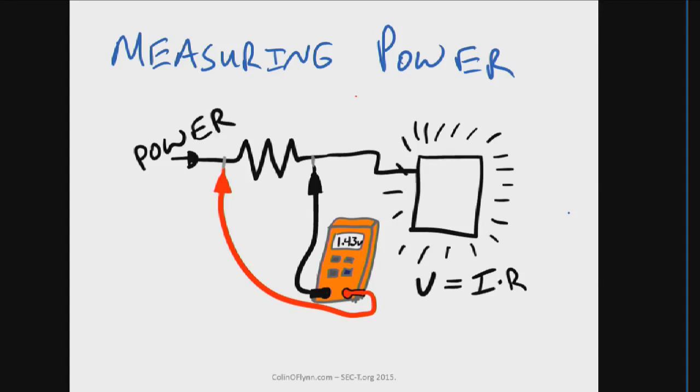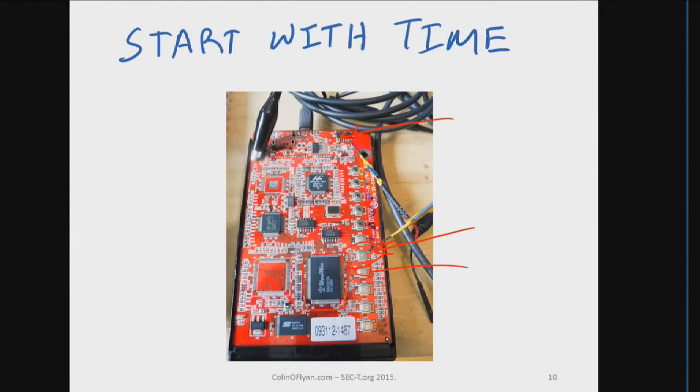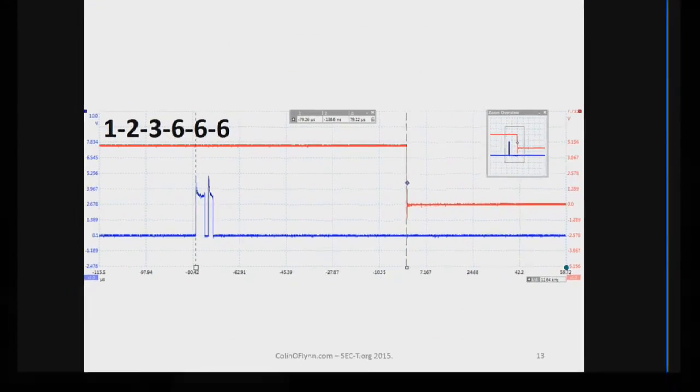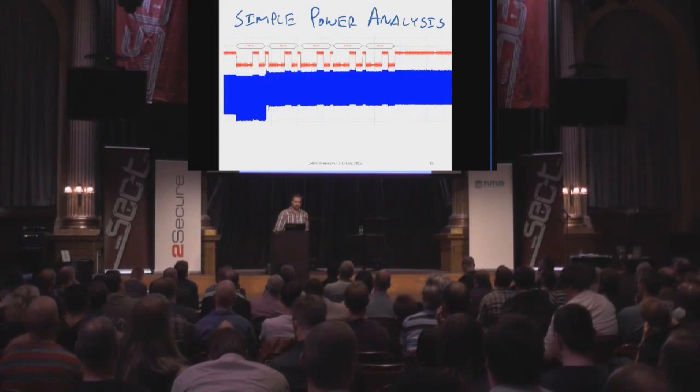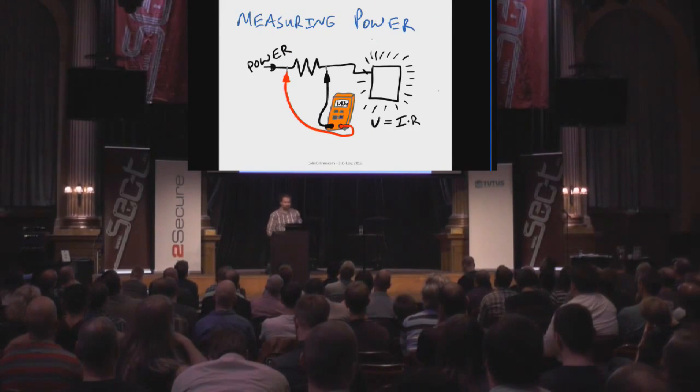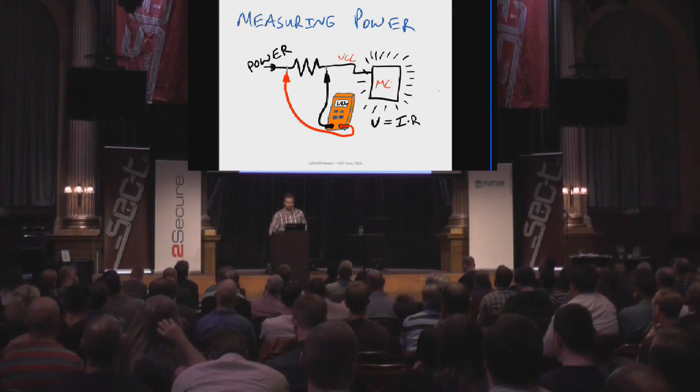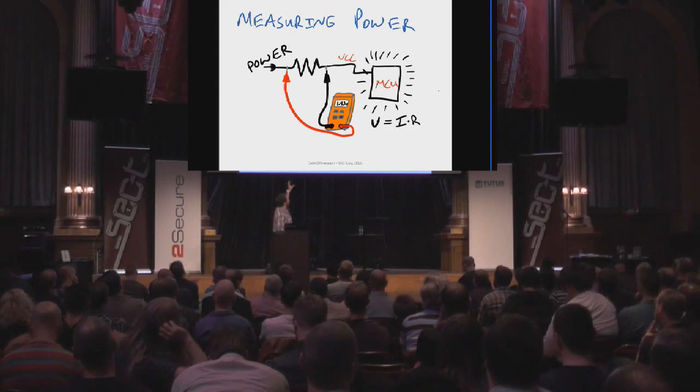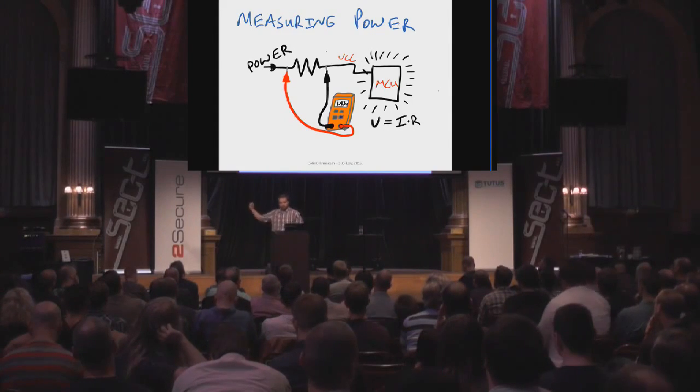For all of these attacks that I'll be talking about, we need ways to measure the power. Very briefly, we have a microcontroller, and there are various chips using power. What we want to do is insert a resistor into the power line, so this would be the VCC pin for the chip, your microcontroller, MCU. And we're just measuring the voltage across that resistor, really with an oscilloscope, not with a DMM. And this is how we get our nice power usage waveforms.